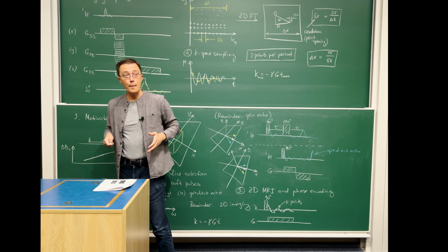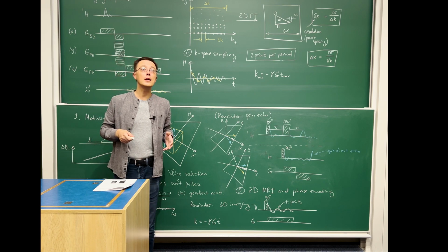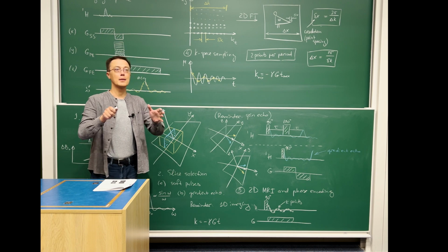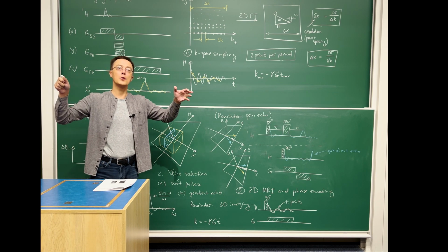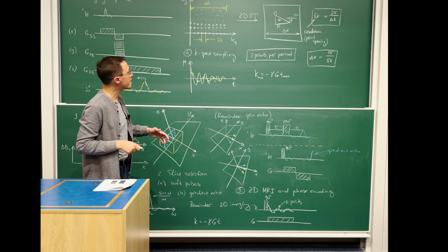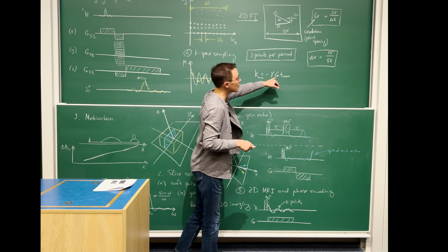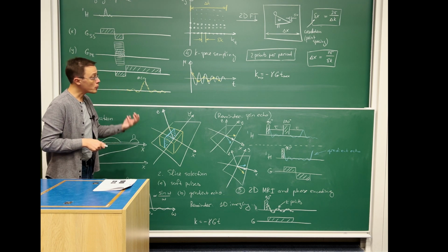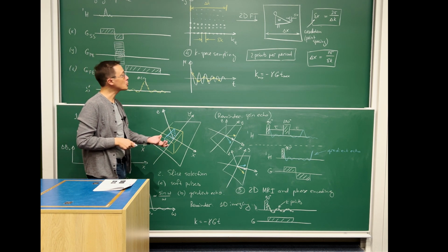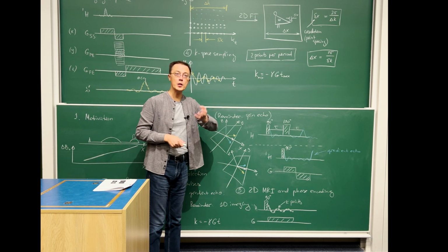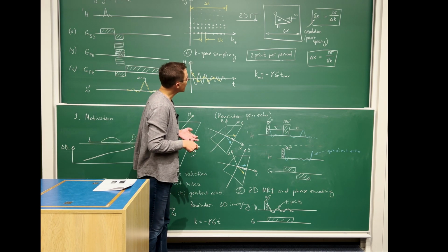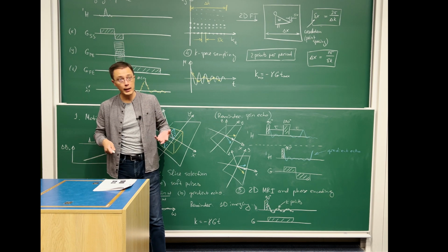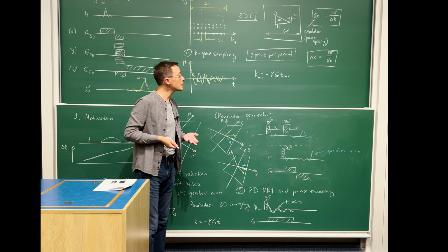And so the banging sound that you hear when you are inside the MRI instrument is in fact the Maxwell pressure trying to pull the coil apart when a very strong current is sent through the gradient coil. So there are firstly electrical limits on how strong a current we can send with what kind of precision, and secondly a purely mechanical limit of how much abuse, mechanical abuse, such devices can handle.